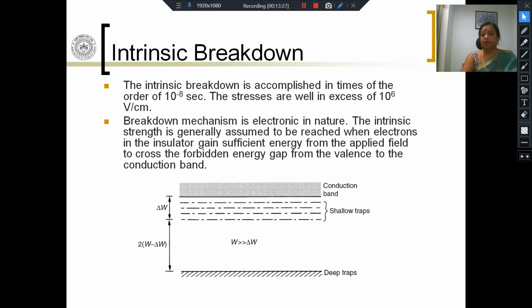So of course, remember, we are not talking about very impure materials here, but only very, very small impurities, and maybe there is a sufficient quantity of energy to take electrons from the valence band in addition to detrapped electrons from the shallow traps and deep traps, which combined give you a sufficient number of charge carriers now in the conduction band.